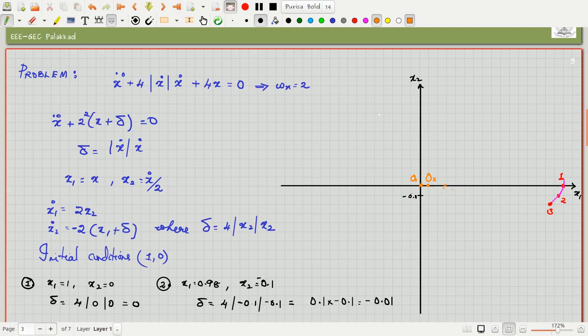When I'm at O3, again with O3 as center and O3-3 as radius, I will draw another arc here. In that way, I will go forward and find all my points. When I move forward, we have to move with short distances so that I get more accurate results.